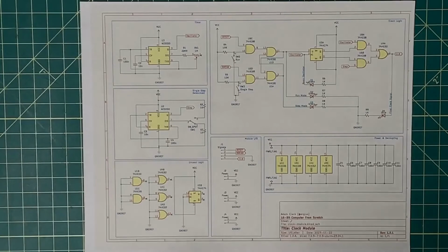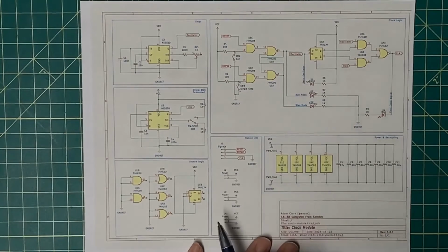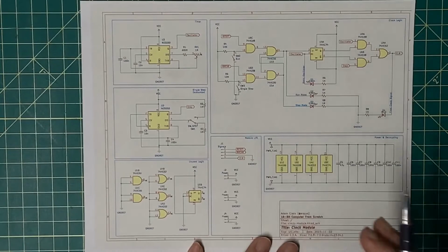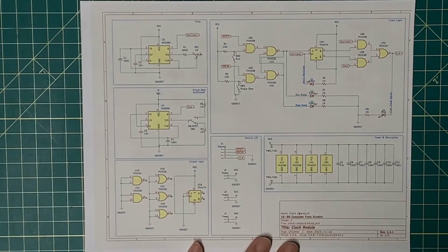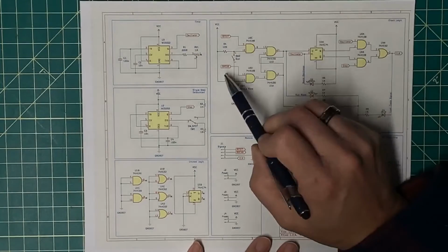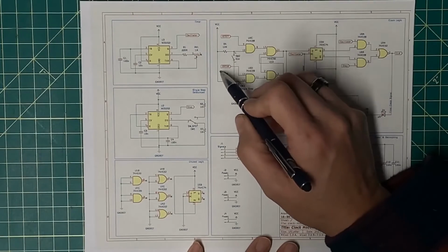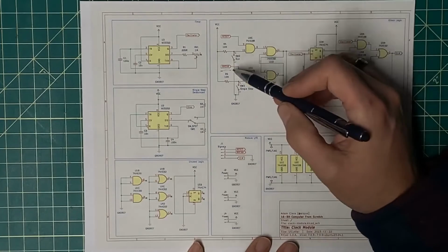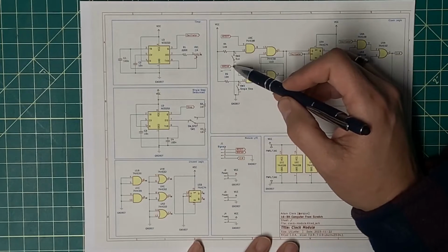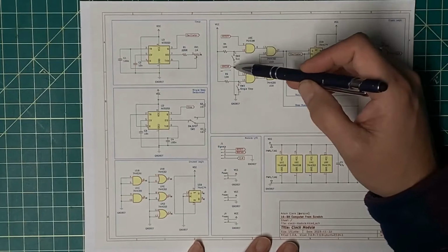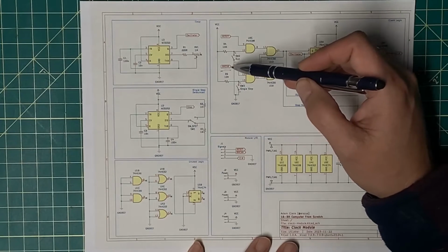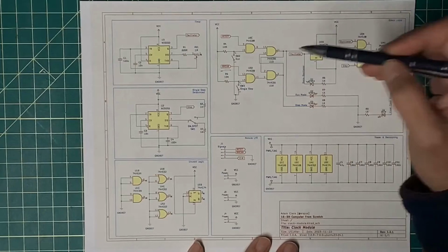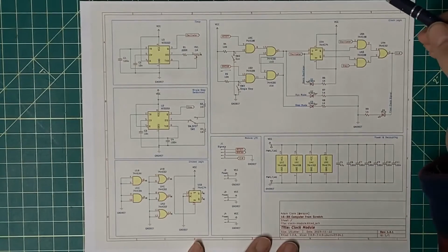All right, slight change of plan here. I'm going to start with the schematic and identify the change that needs to be made so that I can then go back to the emulator and make that change appropriately. Ultimately, this signal is coming in as an inverted signal here into this AND gate. Really, what I need to do is just invert that so it's an active high signal. And then the signal coming out of the inversion is active low going into this AND gate as it should be.